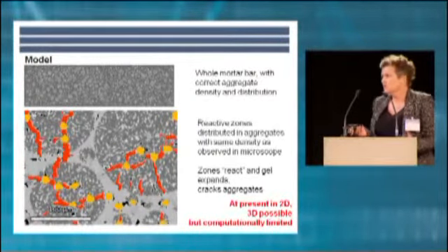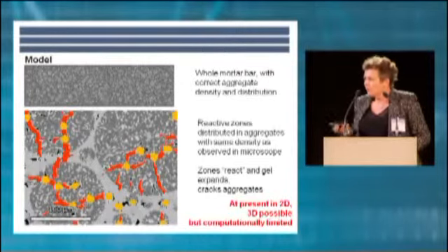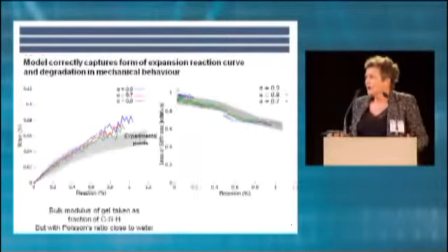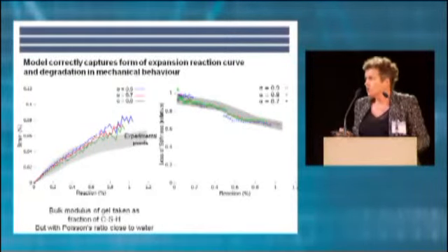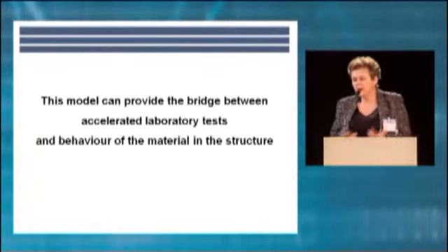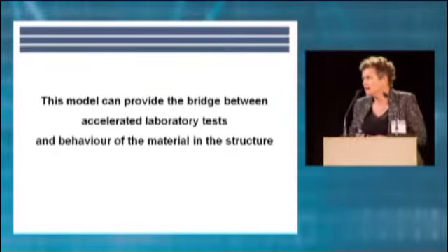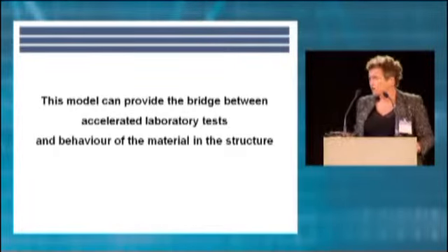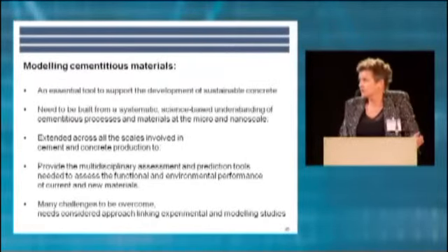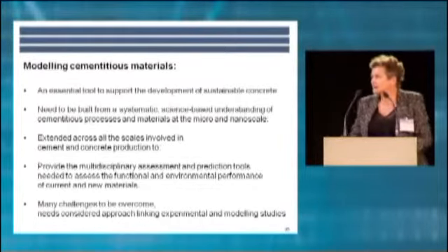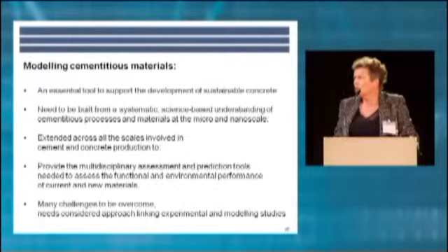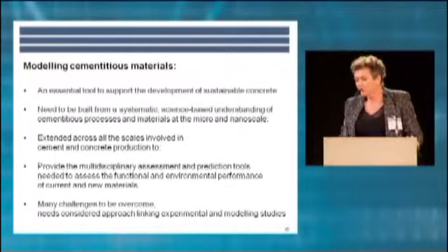We can use this observation then to put together a model where these are the aggregates, these are the gel pockets inside it, and this can then give us very good agreement with experimental results. And ultimately, we hope this kind of model can enable us to bridge the gap between accelerated laboratory tests and behaviors of real structures. So just to finish, to really try to summarize what I've tried to give you some insight into, I think modeling of cementitious materials is really an essential tool to the development of more sustainable concrete.